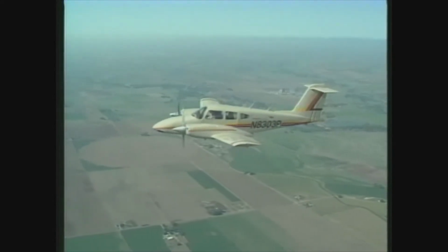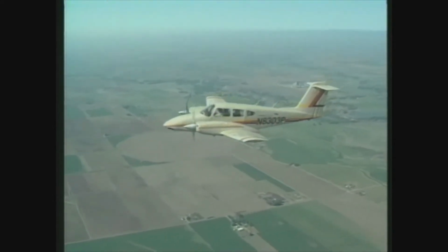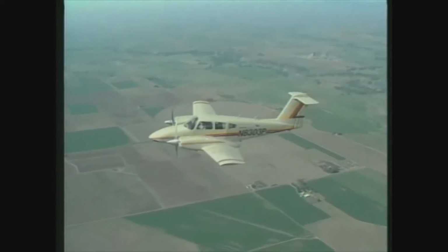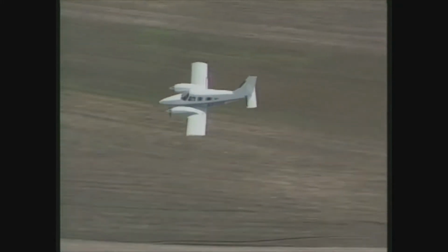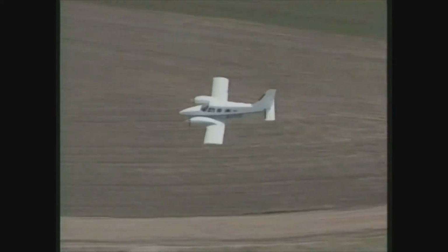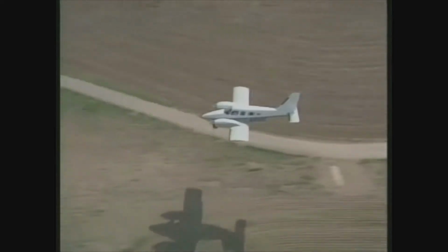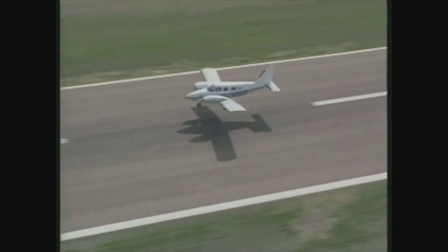Performance planning also is important for the descent and landing phases of flight. With a wider range of operating altitudes and airspeeds, the transition into the landing pattern requires an increase in planning. Multi-engine airplanes generally have higher landing speeds than single-engine airplanes. This causes longer landing distances and makes pre-planning essential to ensure your destination airport is suitable.